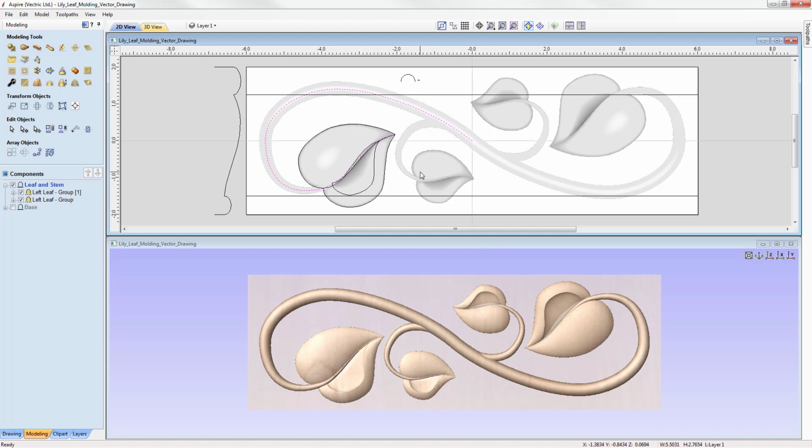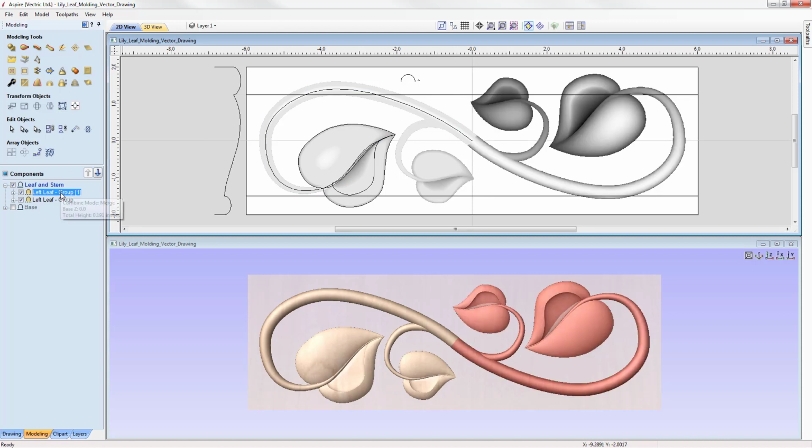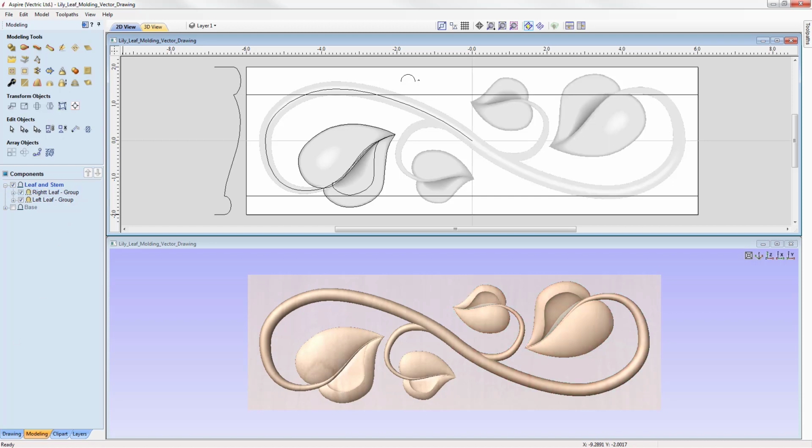And that's all down to the fact that when we originally created this vector in the vector drawing tutorial, we did so whereby we took the control handle and moved it over to the right hand side of the line, so that when we come to create our component from these vectors, they'll blend seamlessly through the center. Okay then, right, so let's just right click to come out of node edit mode, and then we'll come over to our group. We'll just right click, we'll just rename this group, and in here we're just going to call this one right group. Okay, put that in there and then click to accept that.